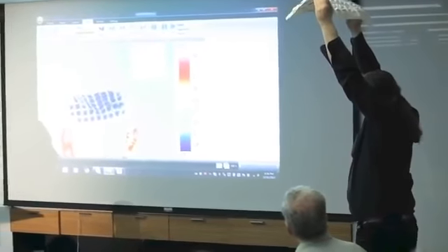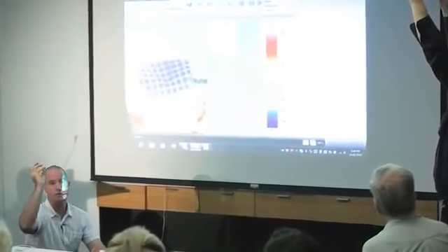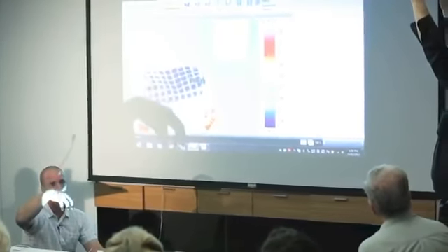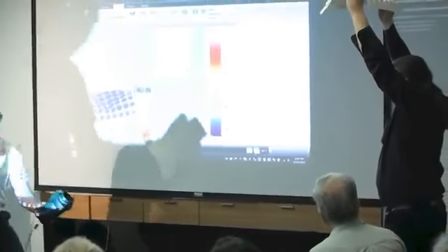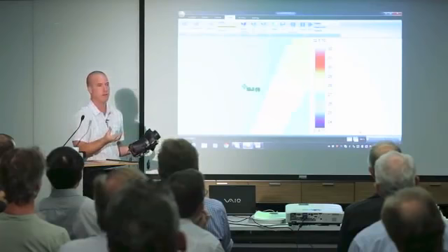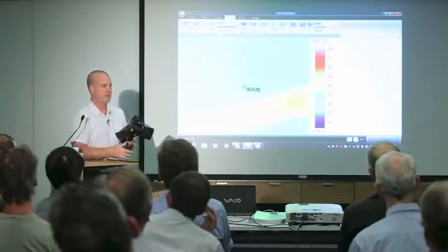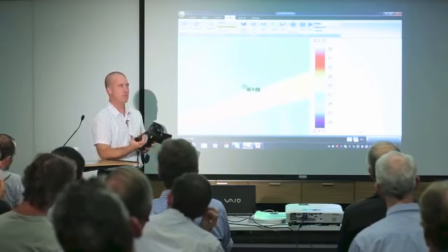Okay, so what you see when you look at the plasterboard ceiling is you actually just see these blue dots all over it because the plasterboard is in connection with the phase change material and it's just drawing the heat through the plasterboard. And by the end of the day, the material might have reached 24 degrees, 25, depending on how well designed the building is and how hot it is outside. It's not a miracle product. It can only do so much, okay?